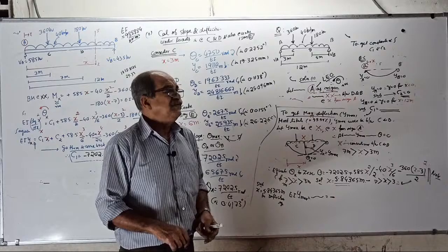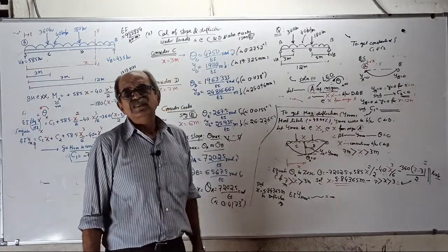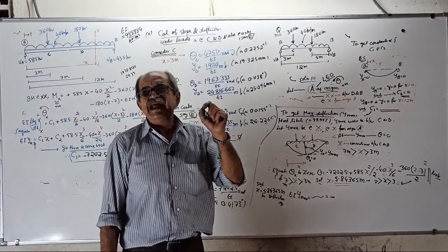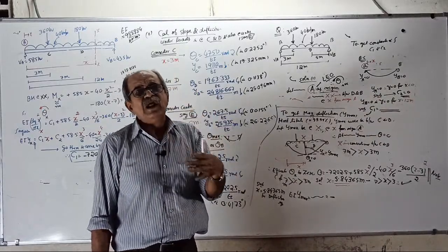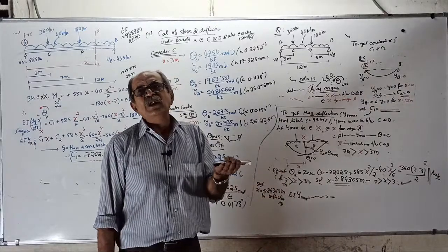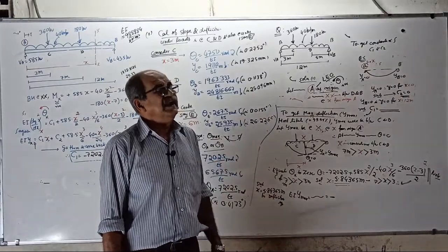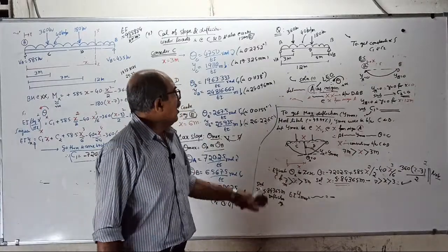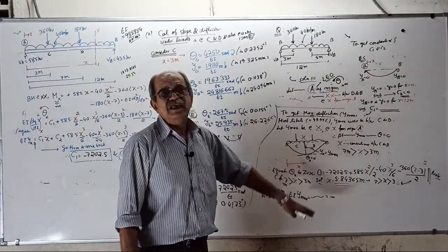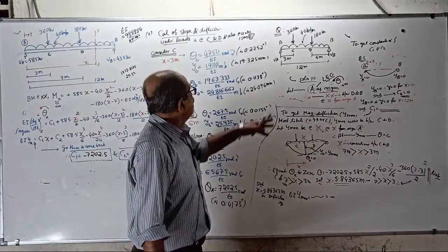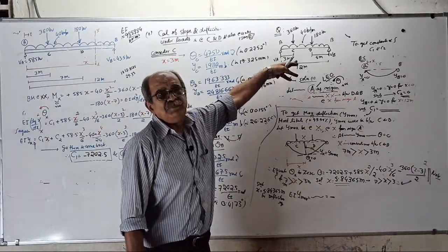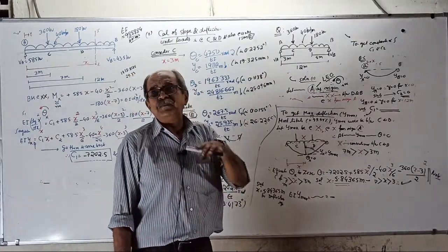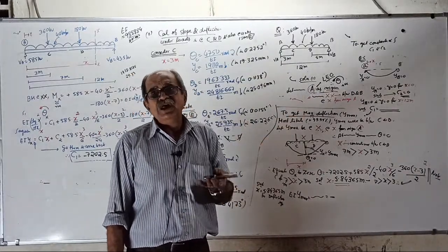What people do is, they won't struggle this much. They will find central deflection and tell, and y max will be slightly more. Actually around 1% more will come. On the safer side, they increase by around 5%. Because all these people will not do practically. If you do manual design, finding deflection at center is easier. Why? Substitute x equals 6 meter. Or if you prepare the model by E-tabs, it will give y maximum.